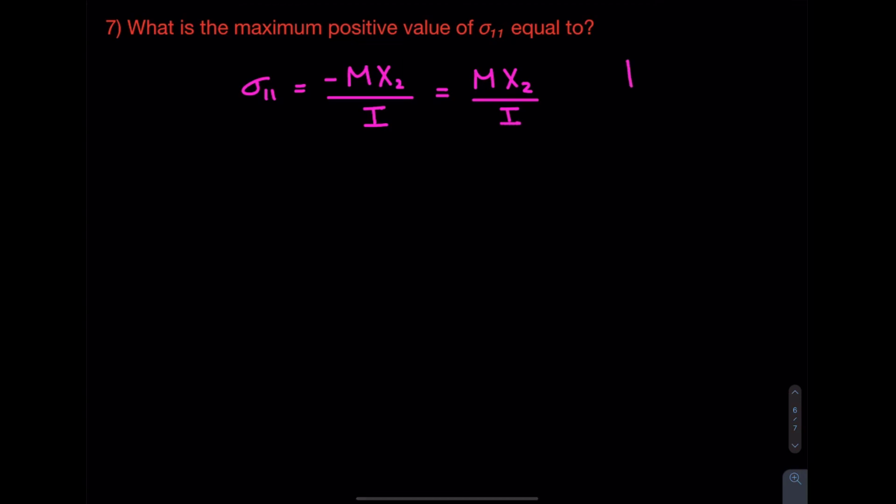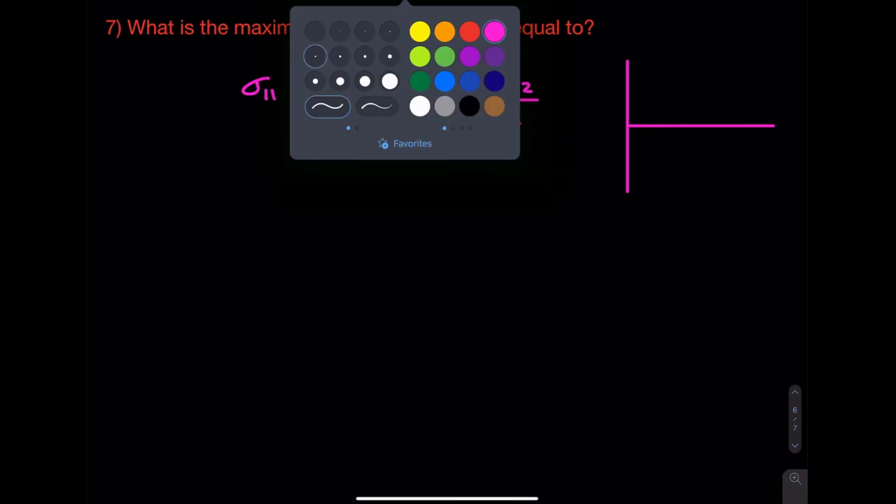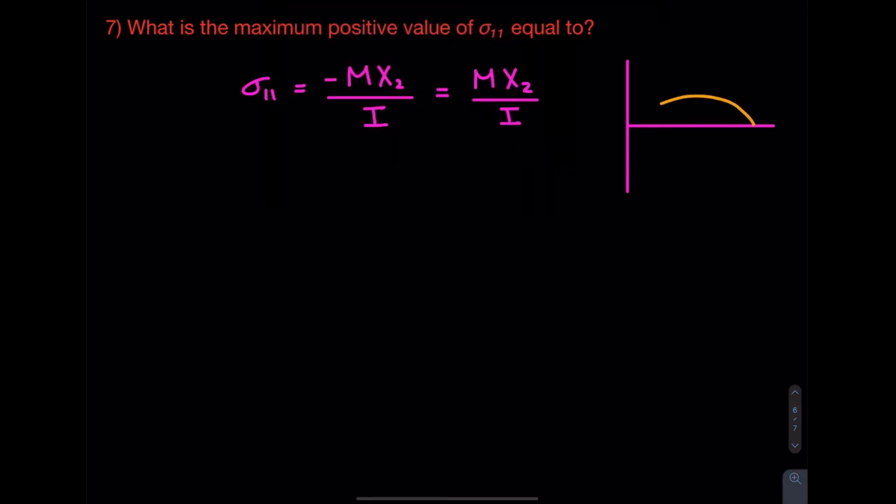Well, we remember that if we have a simply supported beam, and I were to draw the bending moment diagram for it, what we like to do here in Canada is draw it like this, as you know. But then you were in for a rude awakening when you took 372 with Dr. Yong Lee, and he drew all of his moment diagrams like this, the opposite. And this opposite case here, this green case, that's actually what's happening here. So typically this formula has the negative M, but that's why we're taking a negative moment. So the negatives actually cancel.